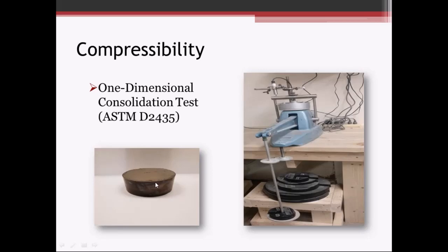But clays are actually charged particles that bind with the water, where sands and gravels are inert. So when a load is applied to a sand and gravel soil, the water trapped in the pores can exit freely, and any settlement would happen immediately for those soils. So typically, settlement of sand and gravel is estimated based on correlations with field data or experience.